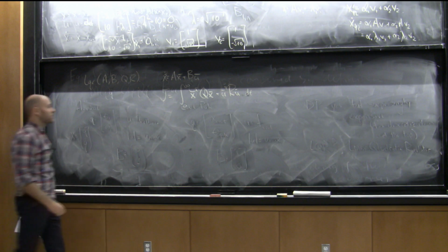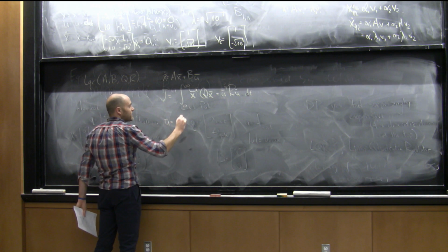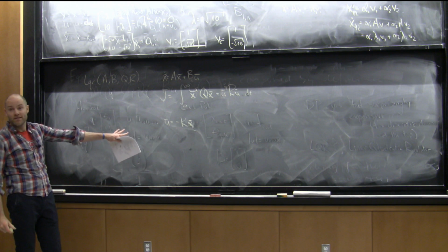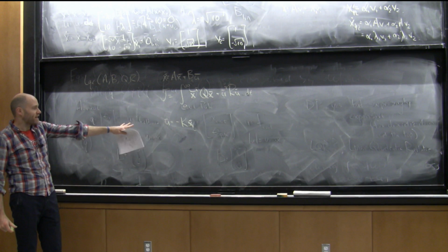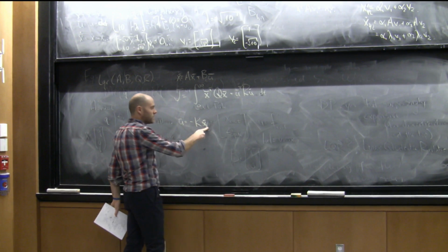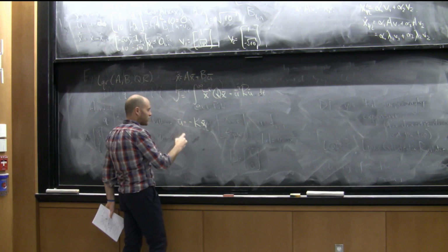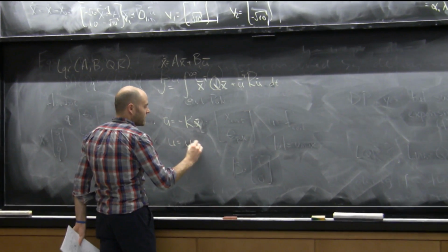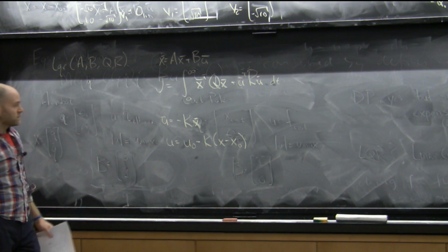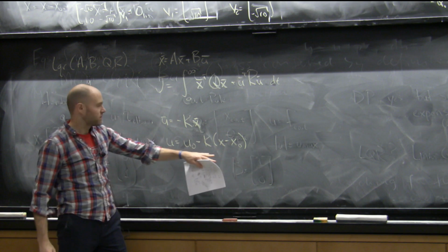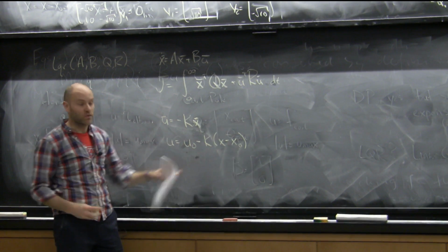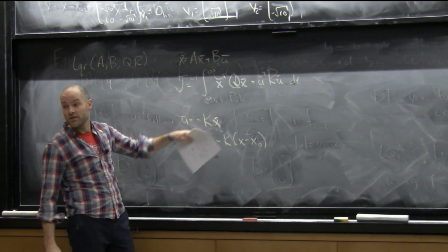So the controller that comes out is u bar equals negative K x bar, which, if you want to type that in now and run it on your system, is actually an affine controller. You know that as soon as I have a constant term off here, it's not a linear function. It's an affine function. If I write this out in the original coordinates, I have to add u0 minus K times (x minus x0). So I've got a u0 plus Kx0 that is a constant term in the controller, and so it's an affine controller in the original coordinates, a linear controller in the, yeah.